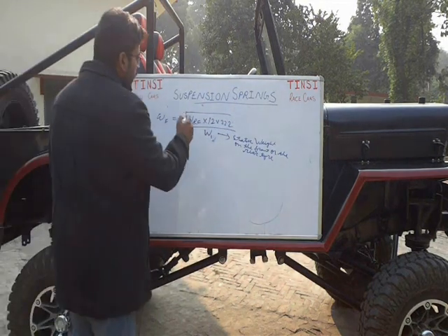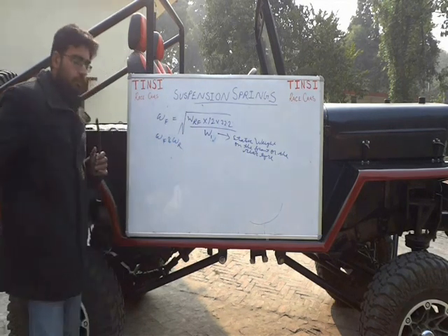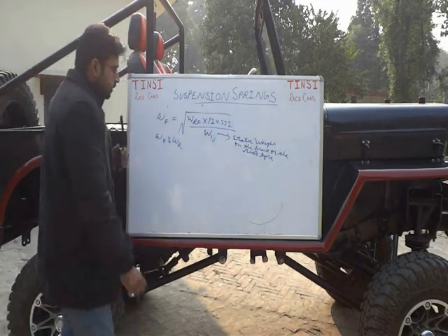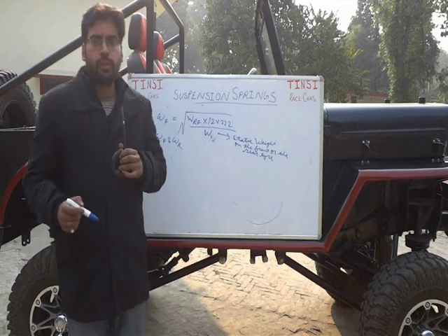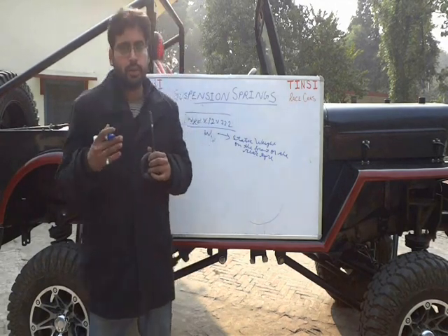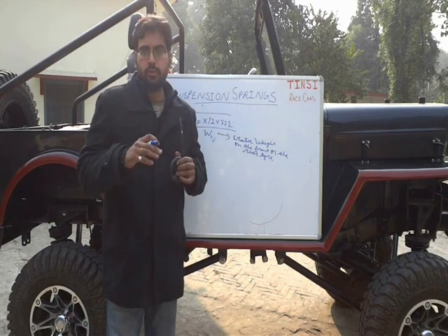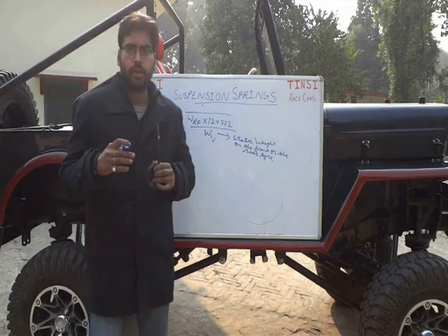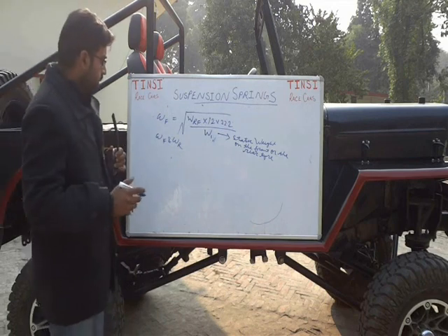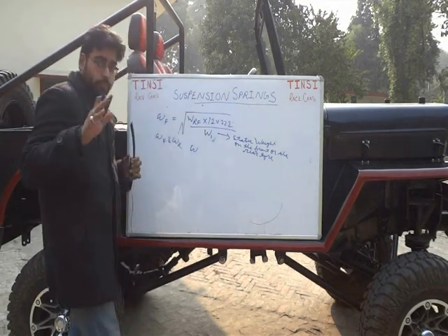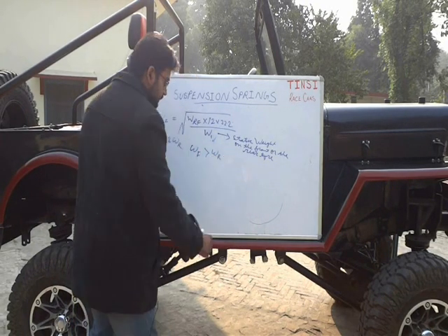So when I find this frequency, omega F and omega R, what I have to see is, because in Formula cars our main aim is neutral steer, you must be knowing neutral, over and understeer. We require neutral steer. As we turn, the car follows it. There is no side stiffness gain or anything, the car just has to follow. So to cater for the neutral steer requirements, for mid-engined cars omega front should be greater than omega rear.